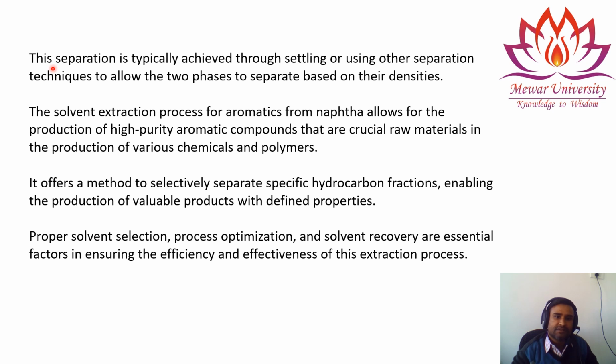The solvent extraction process for aromatics from naphtha allows the production of high purity aromatic compounds that are crucial raw materials in the production of various chemicals and polymers. It offers a method of selectively separating specific hydrocarbon fractions, enabling the production of valuable products with defined properties. Proper solvent selection, process optimization and solvent recovery are essential factors in ensuring the efficiency and effectiveness of the extraction process.